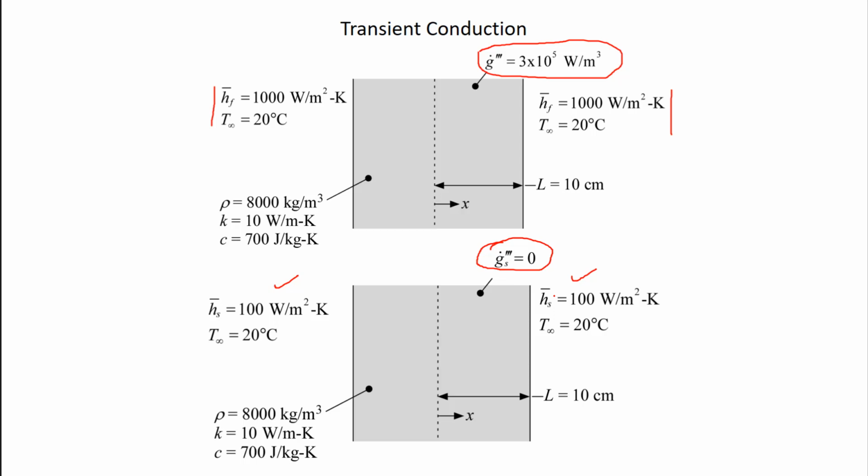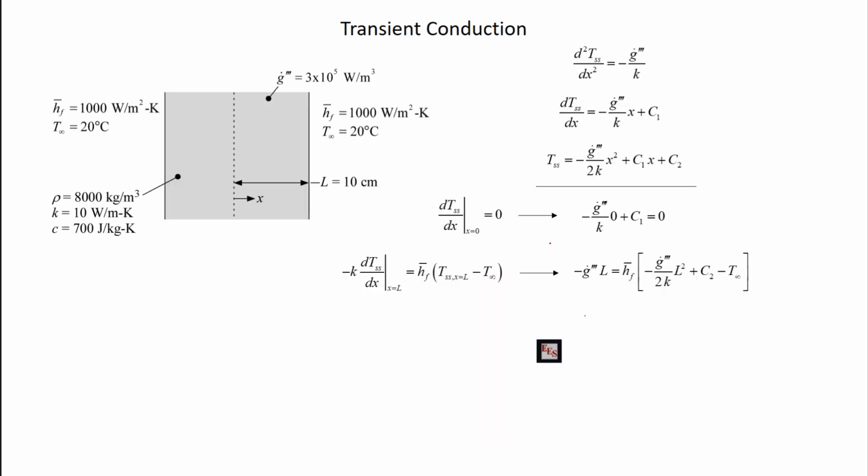So at time equals zero, we have this steady state temperature distribution inside of here that's associated with ohmic dissipation, and then for time greater than zero, this conductor is going to be cooled down to T infinity in some transient process, right? So let's do the easy part of the problem first. The easy part being let's figure out what the initial temperature distribution is, right? The initial temperature distribution we get by solving a problem that we could have solved several lectures ago. It's a steady state one-dimensional problem.